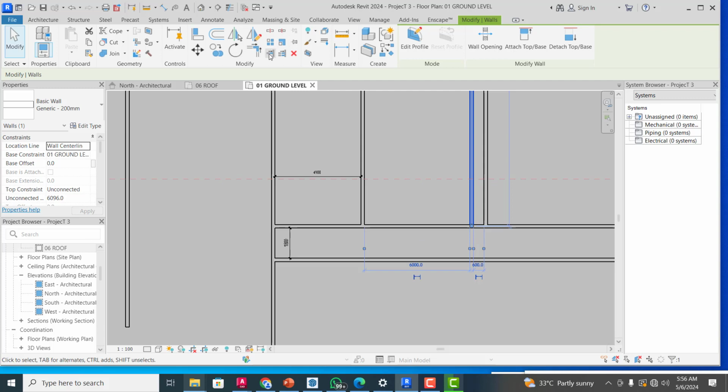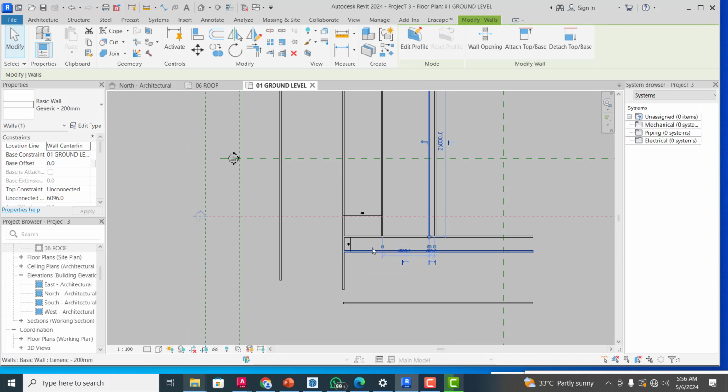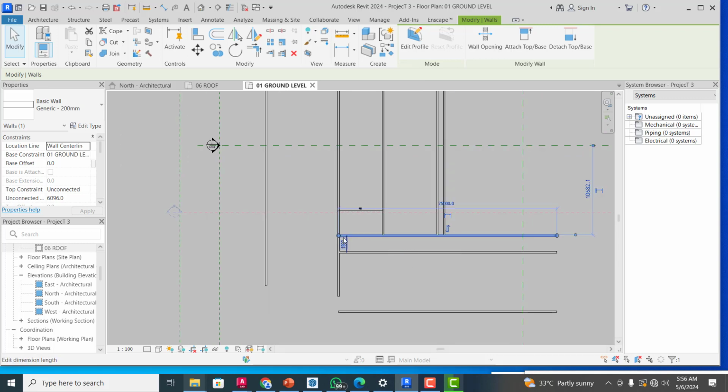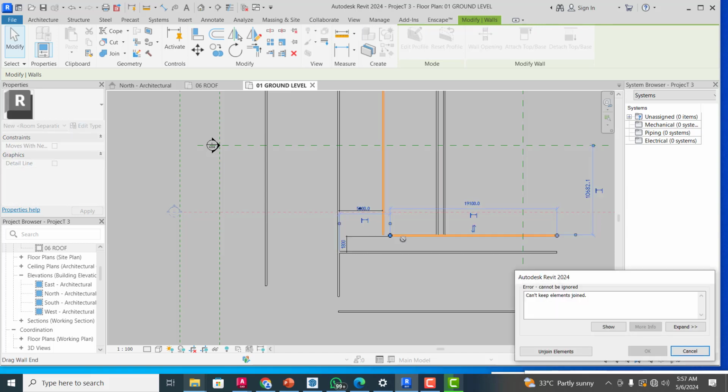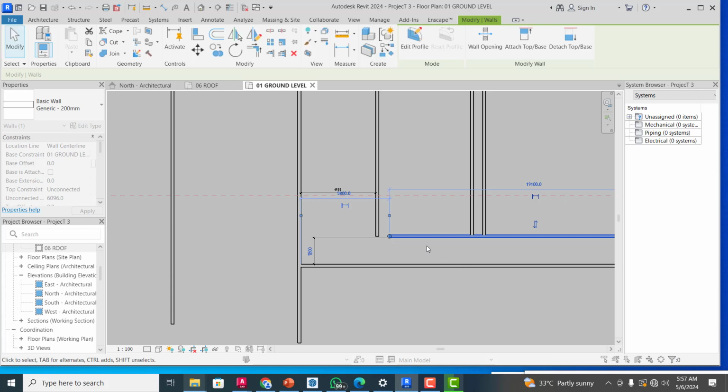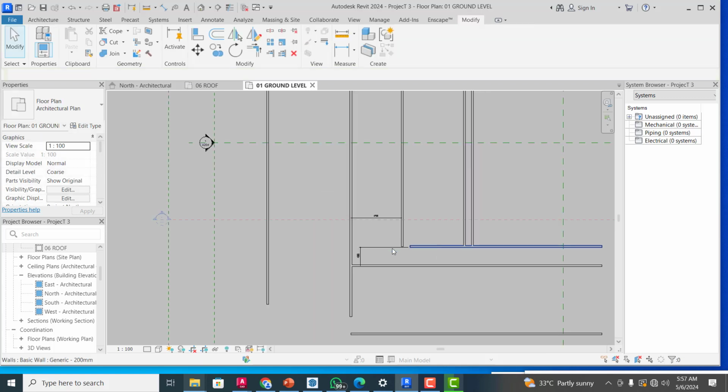And then to do my trim extend rather, let's say I bring this back to this point here, sorry, or let me unjoin this. Let me just unjoin this. All right, so let's say I want to extend this to this instead of this. All I can do now is just to click on my extend, and I'll specify where I want to extend this to. You can see I can just click on this line, and then I will come back here and I'll click on this, and automatically it's going to extend to this particular line.